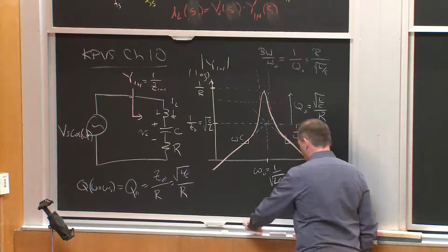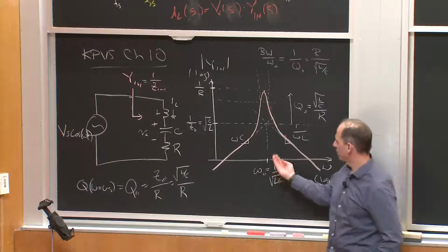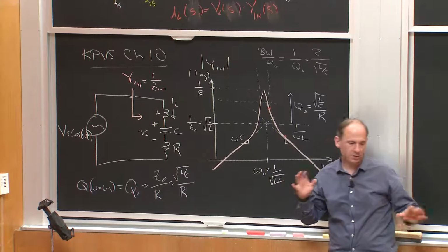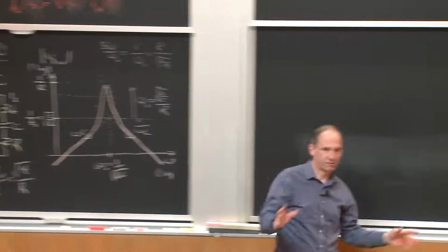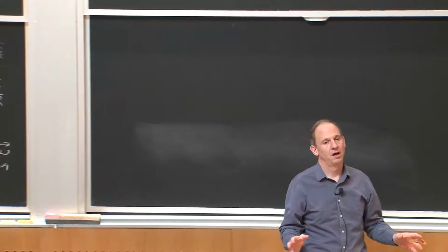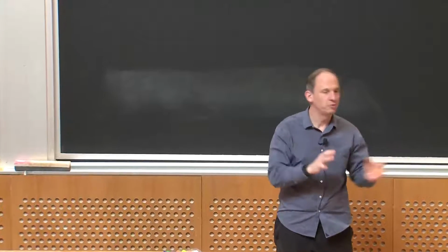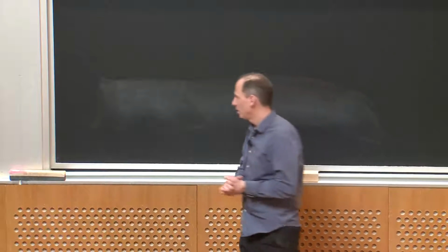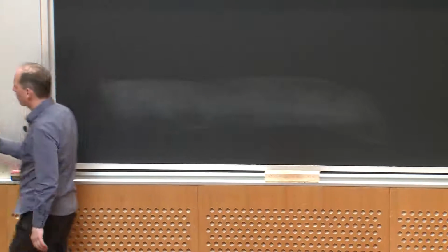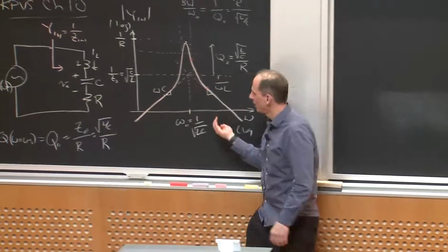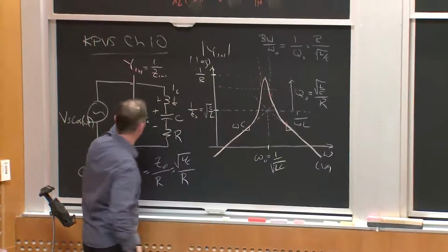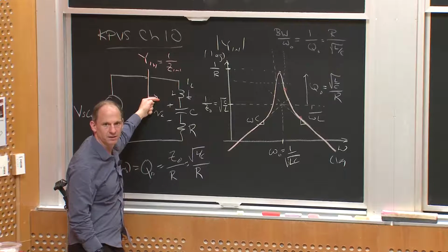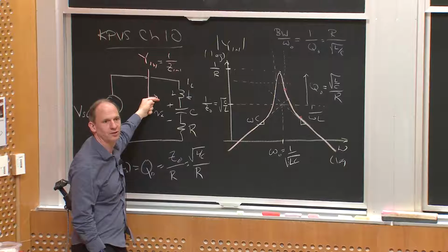All right, well, what would I choose to do? Very often, what we're going to do is run this above resonance, at least for modern devices. And when I talk about resonant converters, they don't have to be soft switched. But frequently you choose this kind of approach because you can make it soft switched. And if we operate above resonance, does the input admittance look inductive or capacitive?